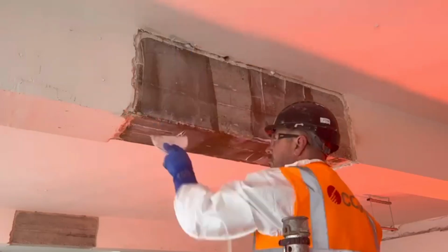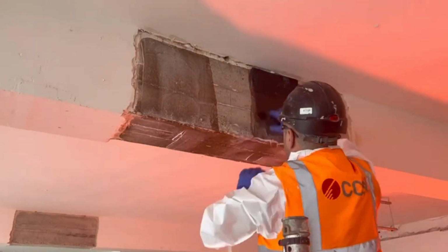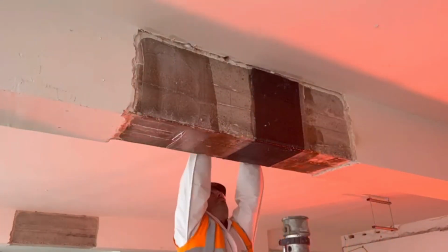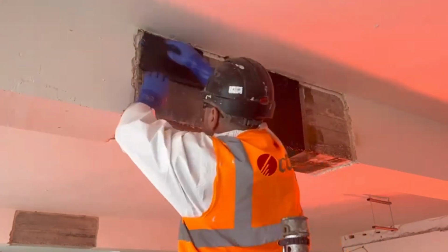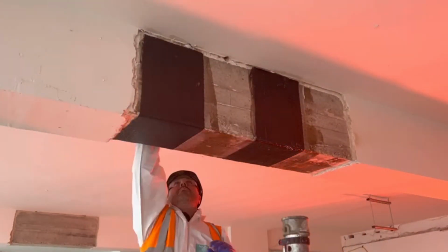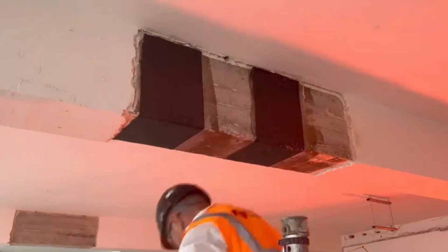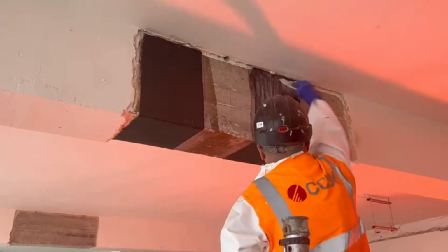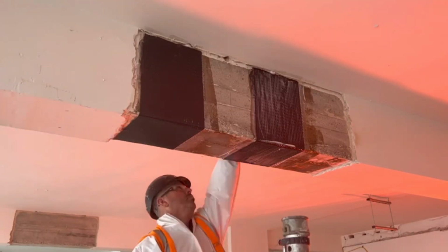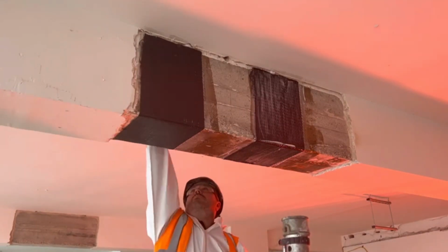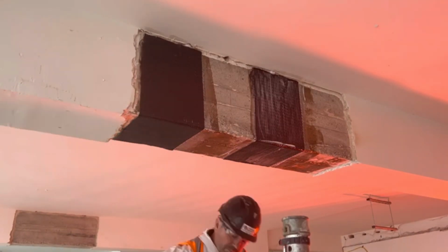So he's putting in the anchors there now on top of the first layer of carbon fiber, yeah? Yeah, so you insert the anchor, you saturate the anchor, put half of that anchor into that drilled hole, then splay the remaining half onto the applied layer of carbon fiber, then put another layer so the anchor becomes sandwiched between layers of carbon fiber, so it's completely covered and will be fully connected with all the FRP there. So that's how these anchors are used.